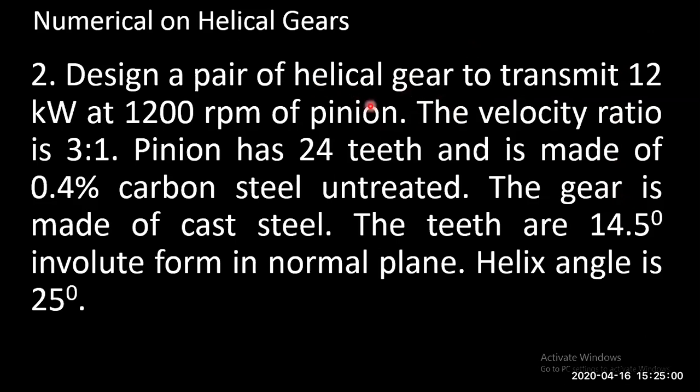Instead of directly giving you helical gear, we may give you a gear which has to operate very silently, or some other data related to a gear which is fully submerged. If you see those data, you have to directly know it is a helical gear. Spur gear and helical gear will be confused most of the time, so you need to read the question carefully and then solve.